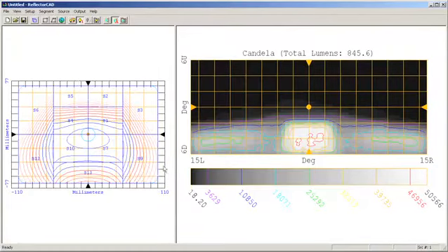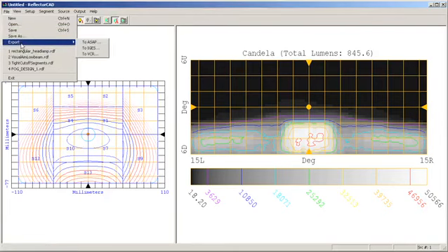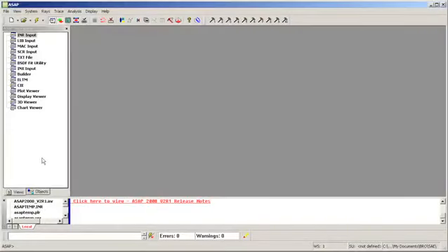I now have designed a segment reflector for a front fog lamp application in literally a matter of minutes. I now have the option of exporting this to either an IGES file or to ASAP for further analysis. Let's now open a file designed in ReflectorCAD. Keep in mind that ELTM can be used to analyze virtually any design that can be imported into ASAP.